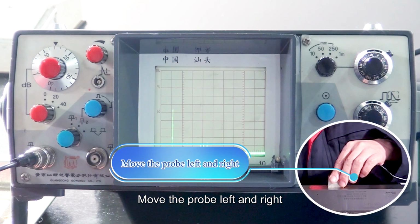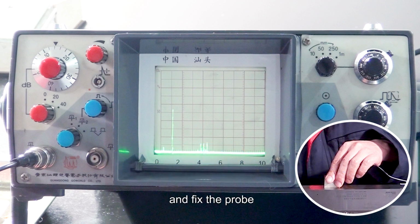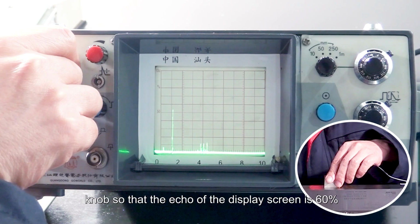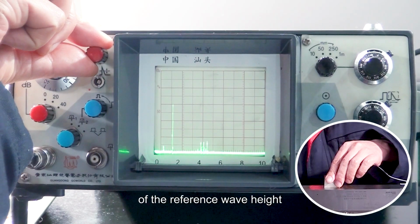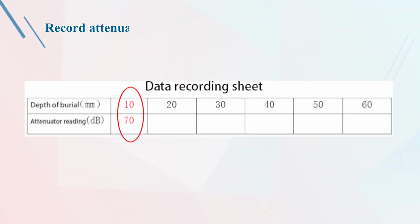Move the probe left and right until the corresponding highest echo appears on the display screen of the instrument and fix the probe. Adjust the attenuator and gain knob so that the echo of the display screen is 60% of the reference wave height.